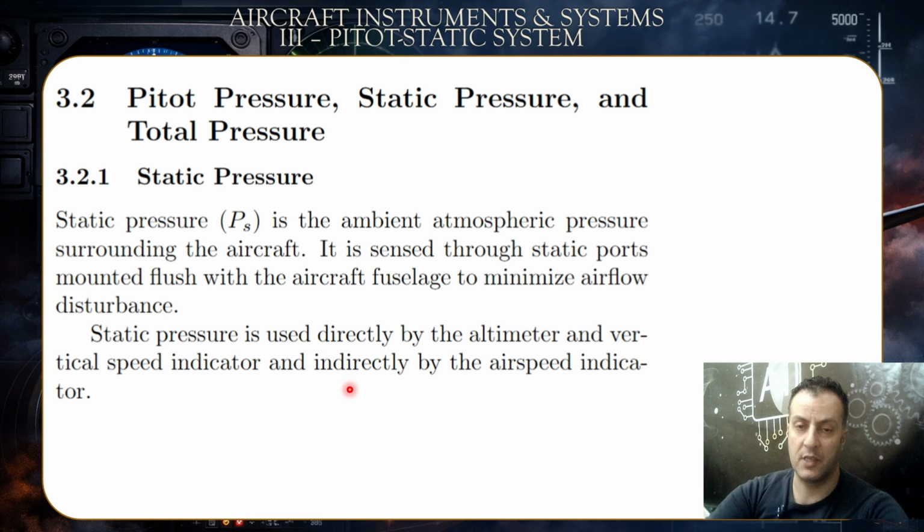This push would give you the dynamic pressure, which is Q equals 1/2 rho V squared, from which, given that we know the exact value of the density, you can get the velocity of the aircraft, which is the velocity of air or the airspeed. The same thing, using this very same formula.